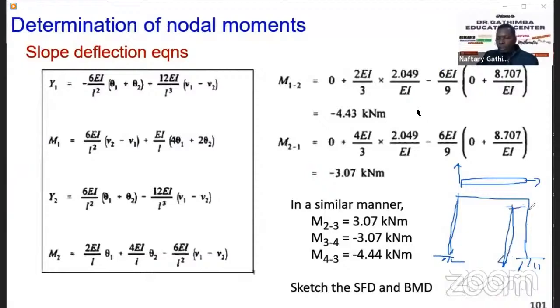So you see this will be the direction Y, and this will be direction X, because this is node i, 3, 4 here. This is node 3, this is node 4. So this is X, this is Y at local coordinate system. So you do the same as we did with this element, and you'll be able to obtain these moments.